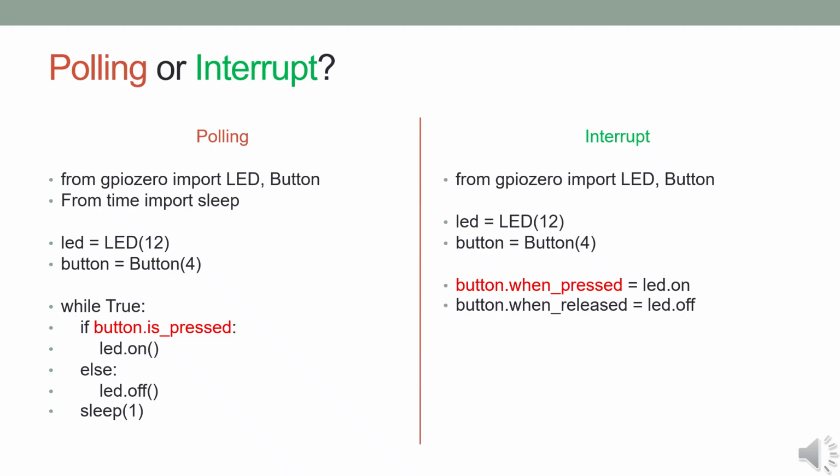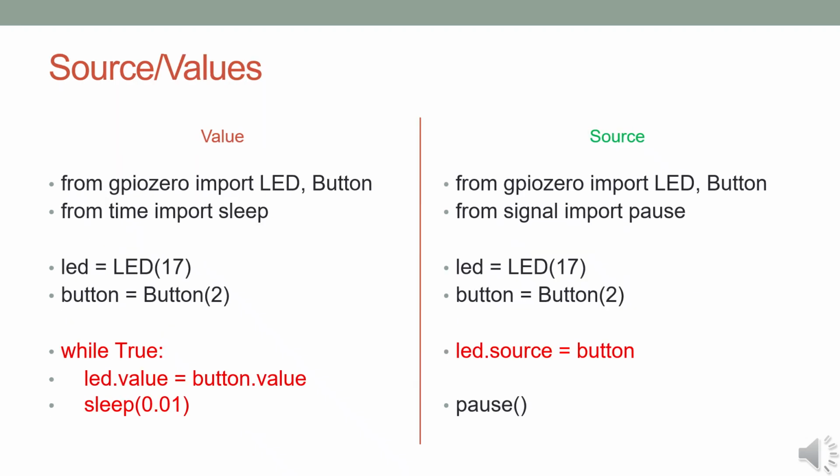In summary, polling is straightforward and useful for small or simple projects where timing is not critical, but it wastes CPU resources and may respond more slowly. Interrupts, on the other hand, are ideal for real-time applications or situations where power efficiency and quick reaction are important. By allowing the hardware to wake up the program only when needed, interrupts offer cleaner code, lower CPU usage, and near-instant responsiveness.